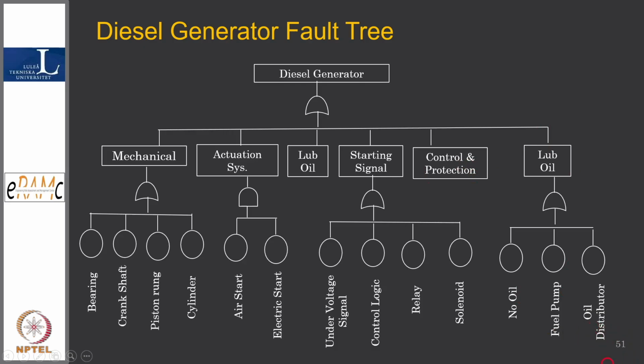Don't you think it has provided a very elegant mechanism for developing our diagnostics? From components into intermediate level, and then finally the basic component level. So with this itself you can create your rule base, and production rules for the diesel generator. And if you implement it, during a situation when class 4 power or offsite power failure has occurred and one diesel has not come, and this particular format was available in an expert system supporting the plant in charge or shift engineer, automatically one of the failed components will come on top.